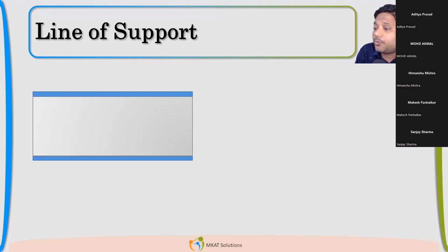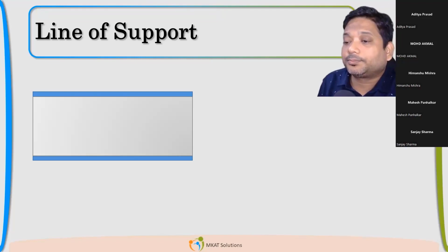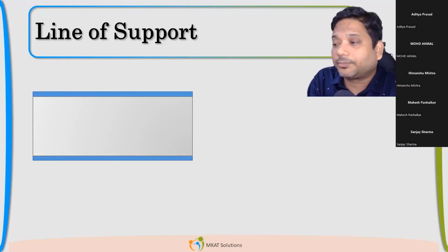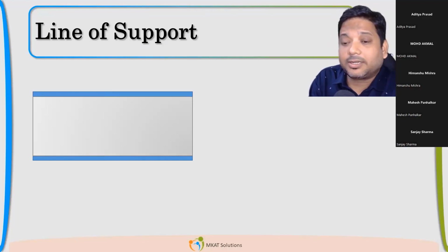Is there any line of support in this cylinder? Say yes, no. Is there any line of support present in this cylinder? Just tell me yes, no. So Istihak is saying no, Manendra, no, right? Correct. So there is no line of support. Line of support means if I try to squeeze it, nothing to stop, right? Unless only the geometry which is resist, the diameter and thickness. There is no line of support present here.